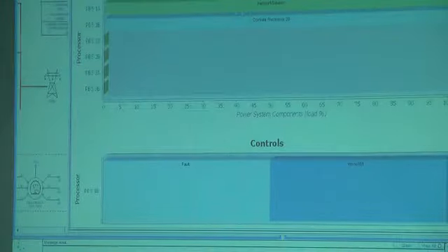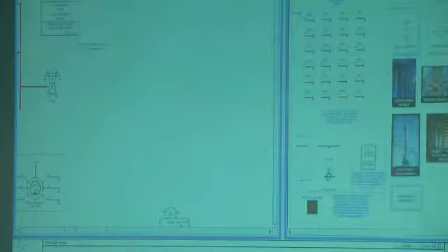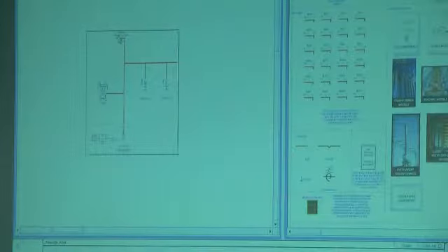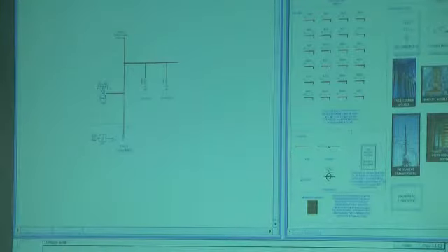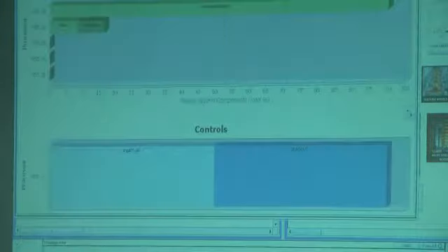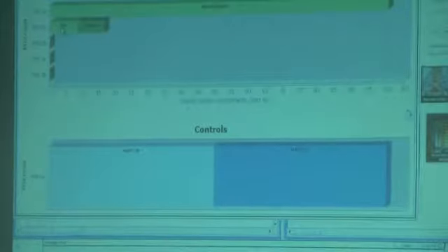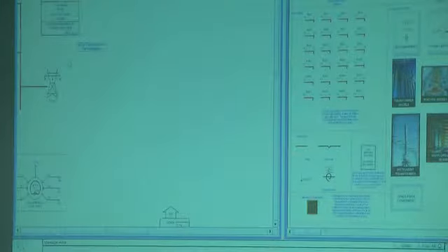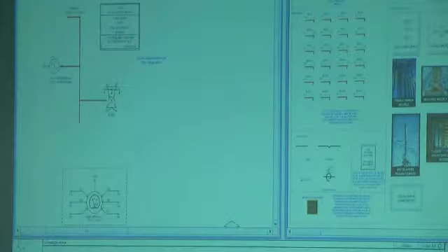But you can see how it compiles. There's a network solution here because I have a bus over here. So this bus needs to be calculated by the network solution. You can see that the T-line is still in network 1. That's because we're in subsystem 1. Wherever this box is is where the T-line is calculated.